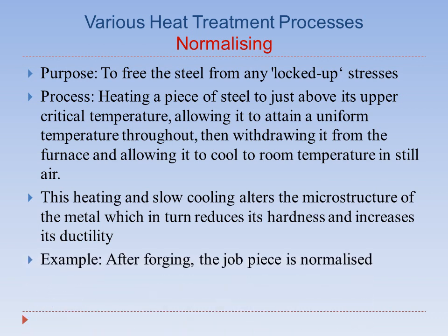For example, when we do forging, the job piece gets hammered for a certain time period, and after getting the desired shape, we know there would be some locked up stresses, and that's why this forged job piece is normalized.